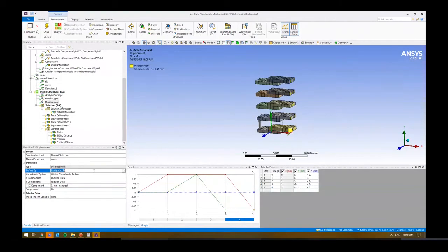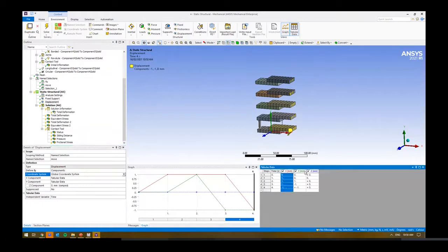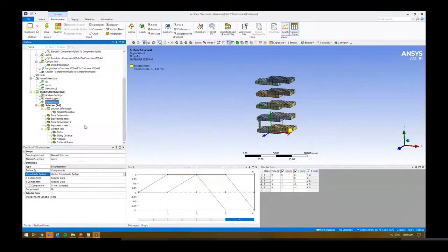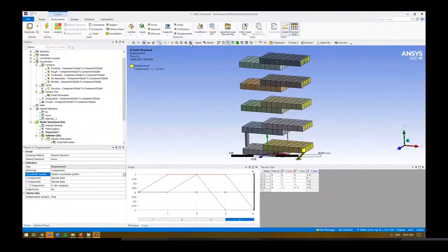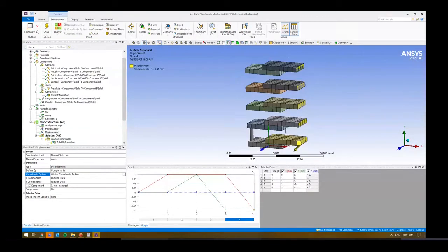If it's cylindrical, you might need to change the coordinate systems. If it's moving in an interesting pattern, you might need to decompose it into X, Y, Z locations, or it might be appropriate to have a joint and the joint simply follows a curve or something like that. So there are different ways depending on exactly what you're trying to get out of it and what motion you're experiencing. So another one from Jimmy.